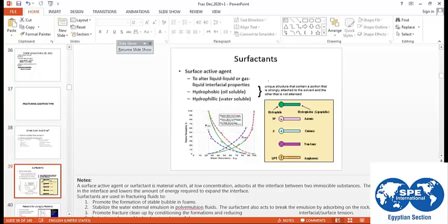So it works like this. You will have a sample from the mixed fluid with the gelling agent, and it should show a certain value of viscosity. This means that your concentration of the gelling agent is correct. You are measuring the viscosity of the linear gel at room temperature, but from these charts you know that this viscosity will be equal to the required viscosity at the reservoir temperature. This way you can select the gelling agent concentration.